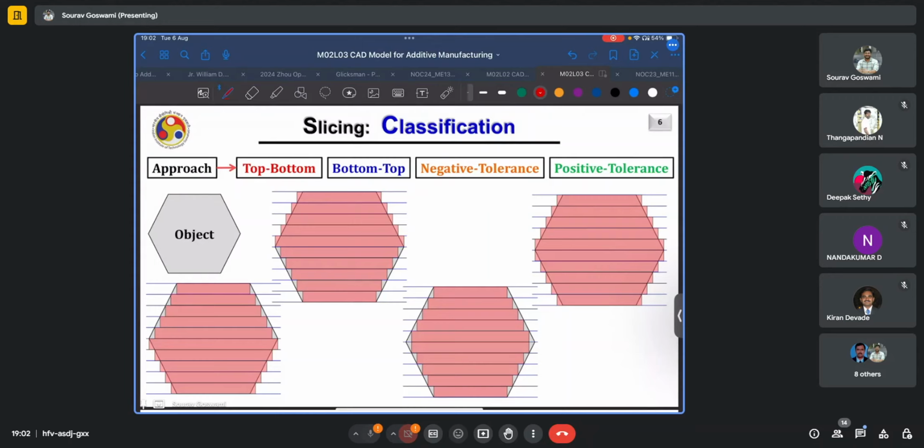But we know the slices, we have the contours, but how do we build the geometry? So I know that, say, for this layer, the contour looks like, say, a square, but how high should it be? That is defined by the layer thickness. But is this height compromising with the geometry as we see here? So in the case of the hexagon,